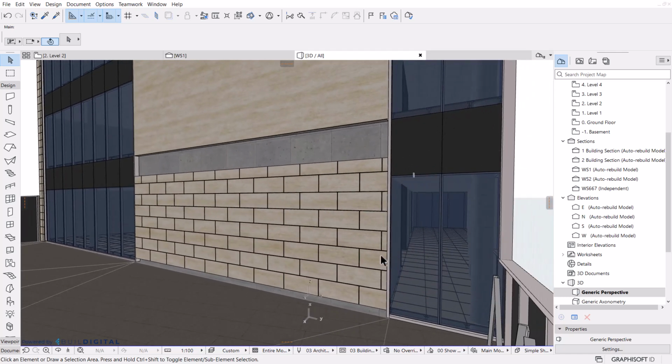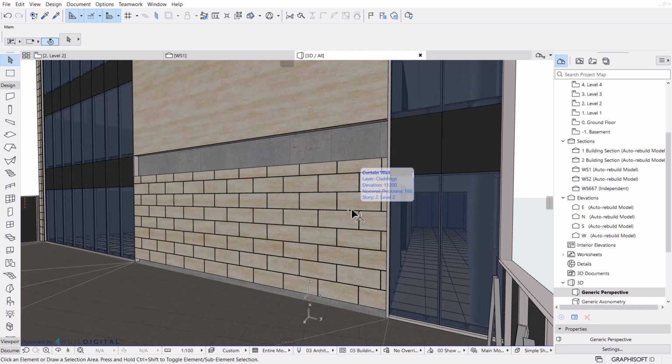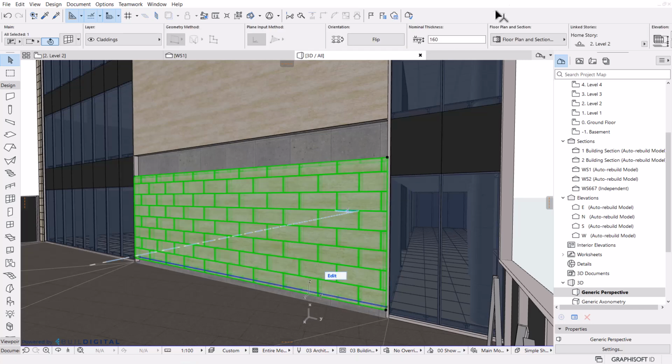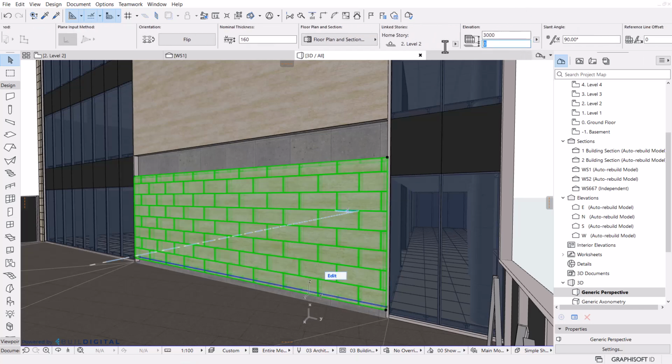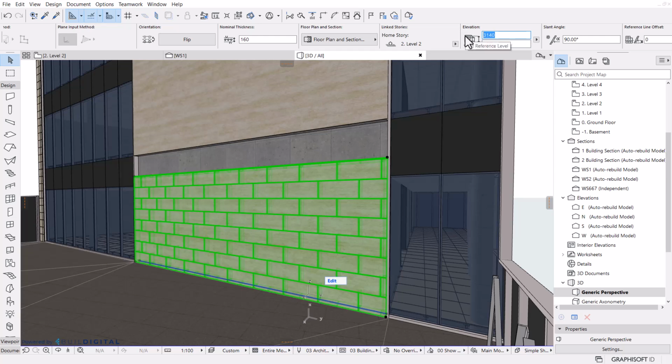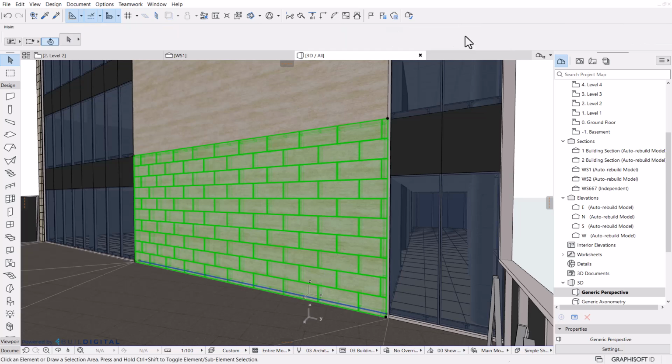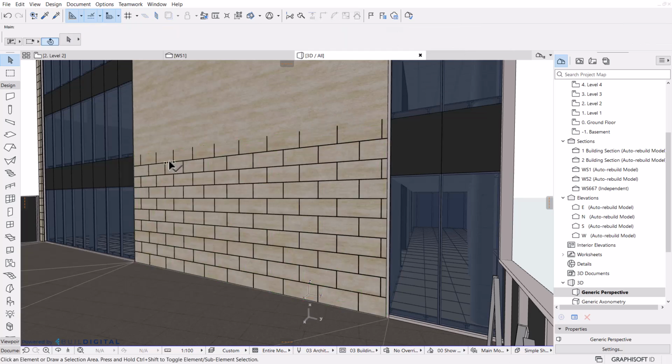Okay, let's adjust the heights in this curtain wall such that it's starting at minus 140 and that the total height, as we know, is 3 meters 890. Therefore, fitting the next level up.